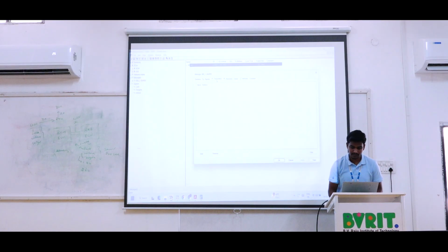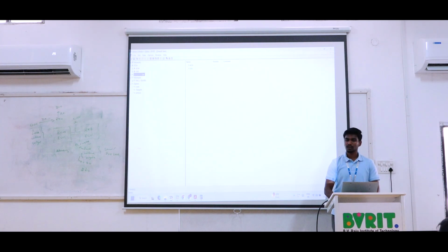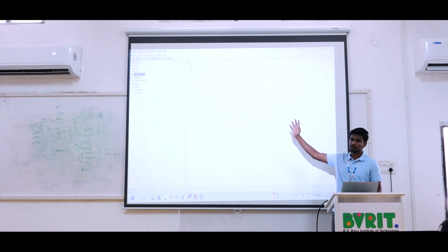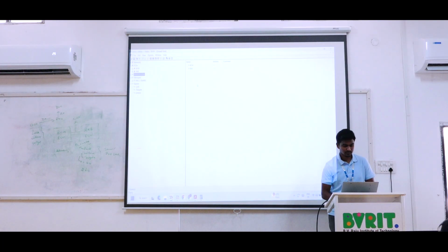So now we are going to set the transmitter and then the receiver ECU. The transmitter we can directly add on the message, where we have the add option. Also we can do it by going to the network nodes. In network nodes we have already added 2 ECUs, one as a transmitter and one as a receiver ECU. Now we are setting RPA as the transmitter. Just double click to open it, or else right click and edit mode.